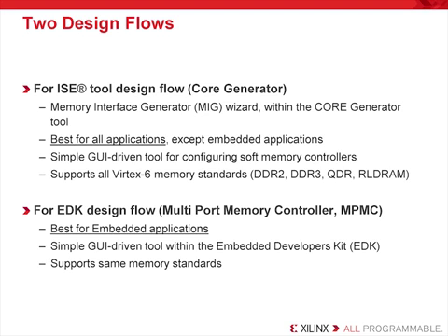As I mentioned, the ISE tools support the use of the soft memory controllers with the MIG utility within CoreGen. This is best for all applications except embedded applications. Embedded applications should use the EDK tools, which give you the ability to add memory controllers when you add the multi-port memory controller component. This is also often called the MPMC component. Like the MIG, it is a GUI-driven utility that makes optimizing your controller for embedded applications very easy. EDK will allow you to customize the controller and attach this component to your system bus without you even having to instantiate the component in your HDL.